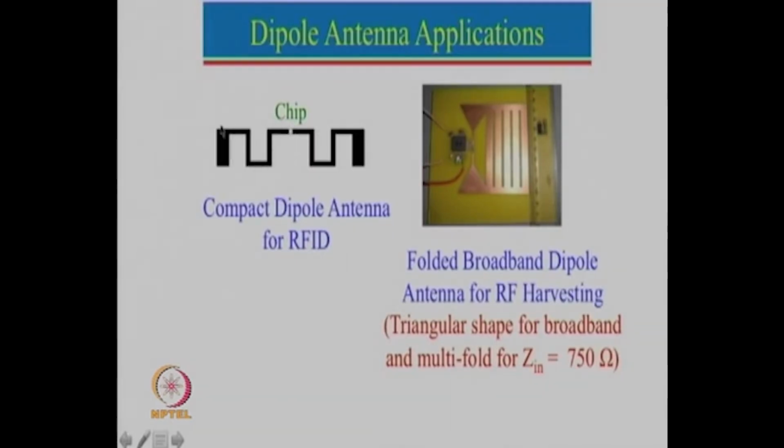Small dimensions will change, and this particular thing is actually fitted. I have just shown it expanded view, but it is actually fitted on, let us say, a small visiting card, and we need to fit the antenna. So let us just take a rough frequency of say 900 megahertz. At 900 megahertz, wavelength will be equal to 33 centimeter. So half wavelength will be roughly equal to 16 centimeter. Now you can't have a 16 centimeter length which will fit in a visiting card.